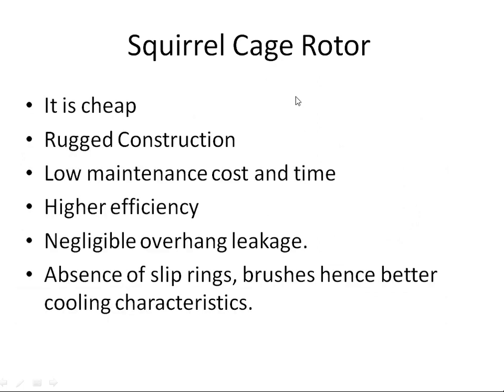This squirrel cage rotor is characterized by its cheapness. The construction is very rugged. It's tough construction, so the performance characteristic is very good. We can have good overload capacity for this type of motor due to its rugged construction. The maintenance cost for this particular type of rotor is very less.